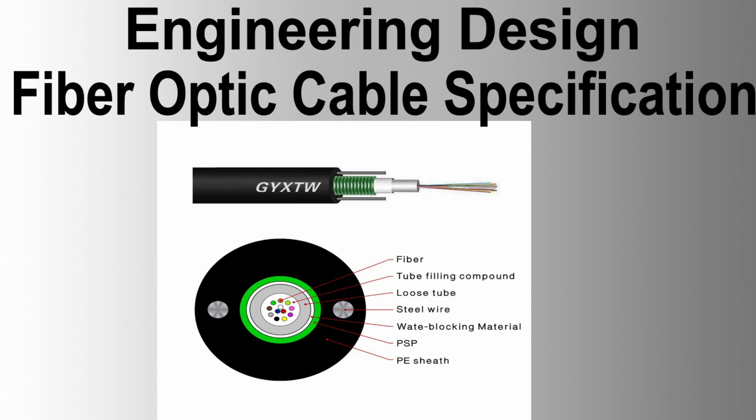Technical requirements of fiber optic cables. Cable construction. Central strength and anti-buckling member. The required cable includes a central strength and anti-buckling member made of 2.5 mm GRP, subject to vendor design. Superabsorbent polymer yarns. These are wrapped around the central member, or superabsorbent polymer binders suitably located elsewhere in the cable